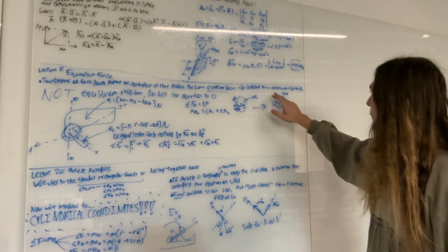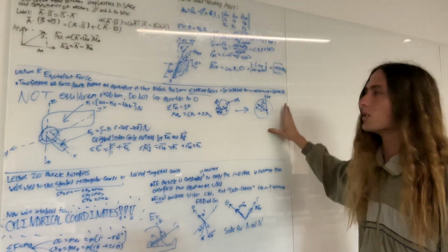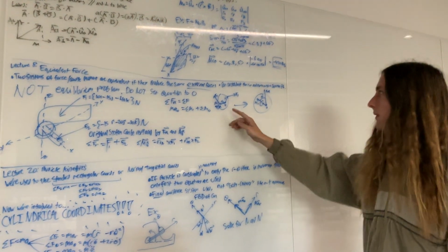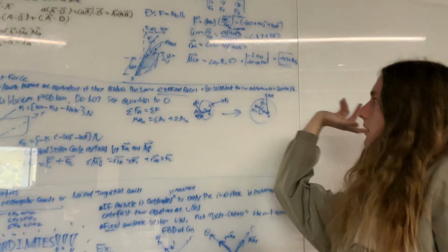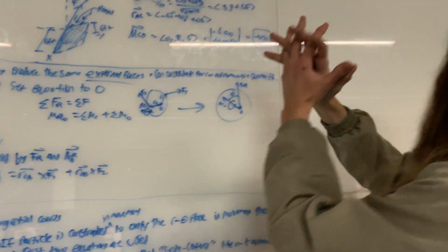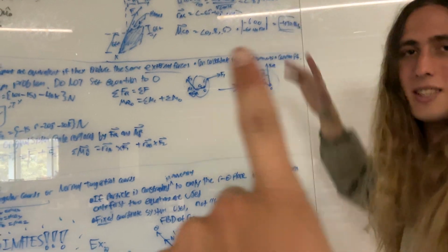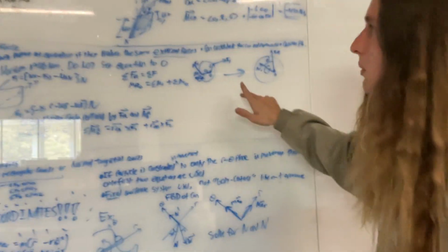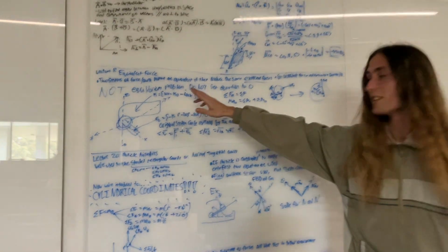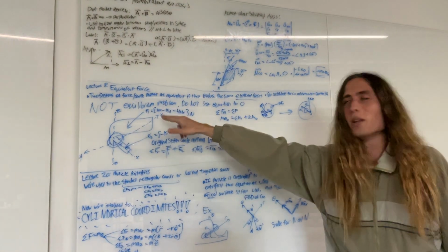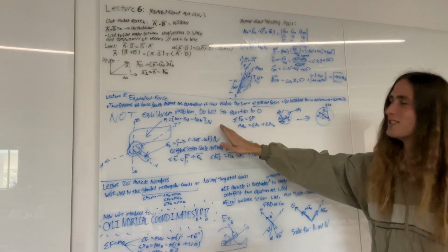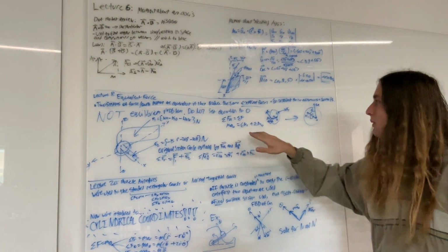You can also consolidate forces and moments to a common point. So really quickly, here's a diagram. You got a force going there. There's a moment. You can condense that, right? Boom, boom. You got one force and one moment, and that's easy to work with. As I touched on a second ago, it's not an equilibrium problem. Do not set the equation to 0. It's not the same thing for equivalent force.